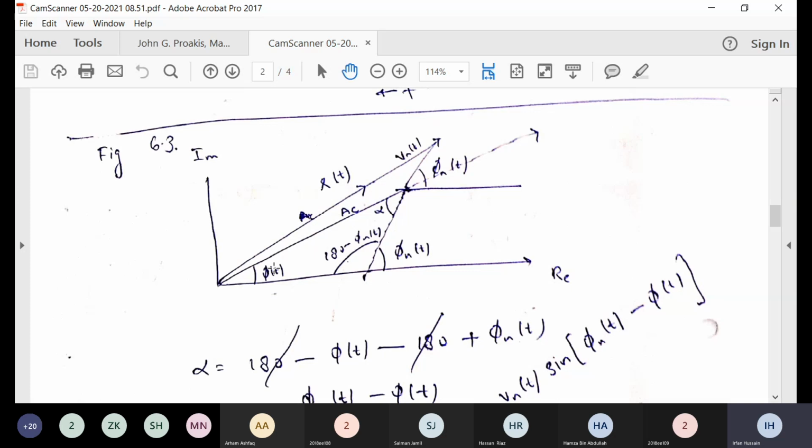So I can write my modulated signal as Ac cos(2 pi fc t + phi(t)). In the phasor diagram, 2 pi fc t is there, but what is the phase other than 2 pi fc t? It is phi(t). So I can just write my modulated signal as Ac with an angle of phi(t). But 2 pi fc t is present for all the vectors.